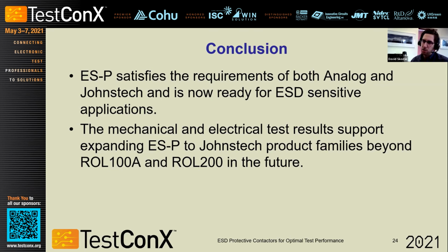In the research that I did, my sources suggested, and I have references on the last slide here if people would like further reading, that at least in the short term there's going to be a higher percentage of devices falling in the lower withstand voltage range. I'm not sure if the actual voltage limit is going to continue going down, but based on the sources that I cited, there will be more devices falling within this ESDS low voltage classification.